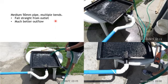So the fall starts right from the outlet. And look at the level of that tray. It's empty. This is 40 liters a minute. I can tell you that that's a lot of water. And that tray is empty. As it comes into the tray, it disappears. And what I found was that never mind the configuration of the piping, if I had a fall right from the get-go and continued outwards, I had a vortex effect, and I had the discharge pipe actually sucking the water down into it once it had started to flow.